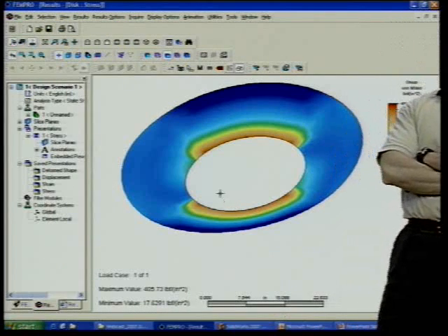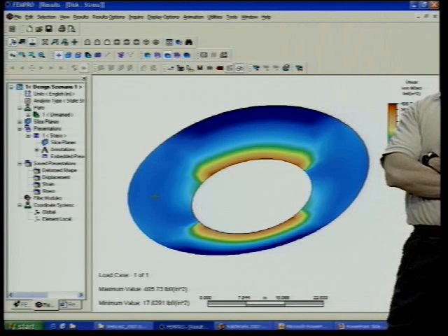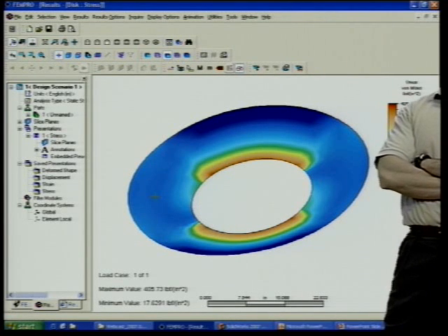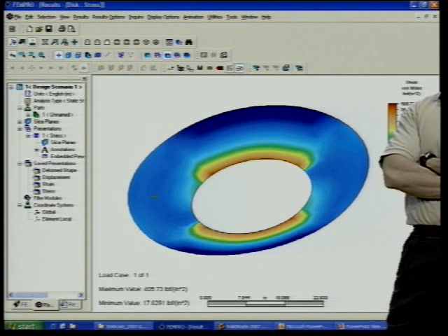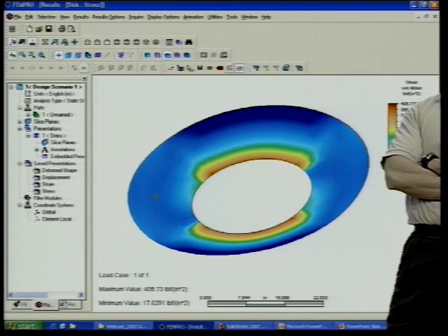And these are the kind of stresses we get out of this, even though this is a symmetrical model. If this was plate elements, straight plate elements with isotropic material, you wouldn't expect to see such a pattern for stresses. It should all be concentric circles.